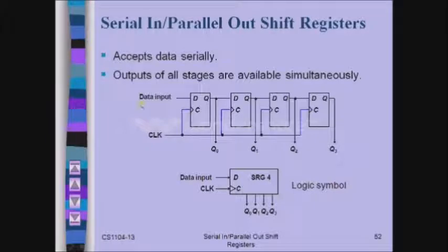Now I am giving the next data input, that is 1, therefore this 1 is processed by this flip-flop, and the 1 which is present at Q0 in the earlier stage, that we got as output, is processed by the second flip-flop. Therefore during the second rising edge, the output at Q1 and Q0 would be 1 and 1.